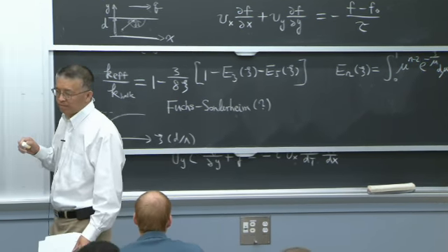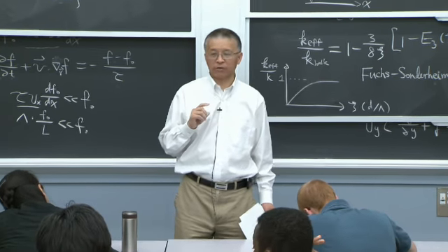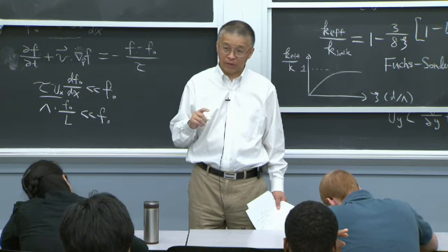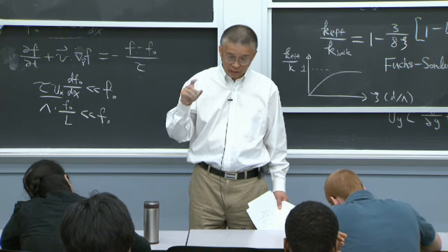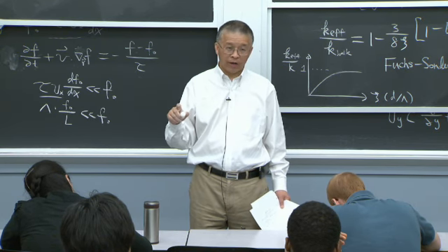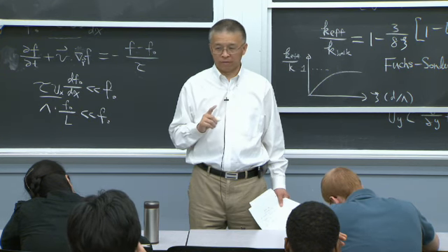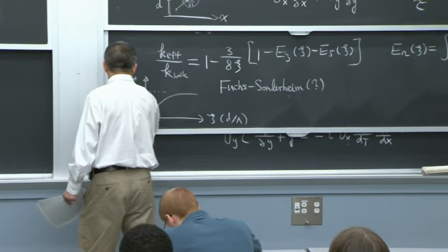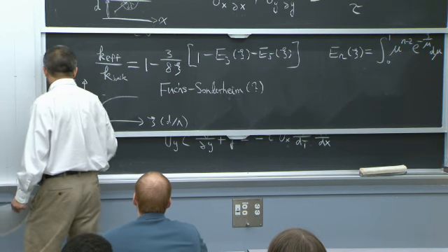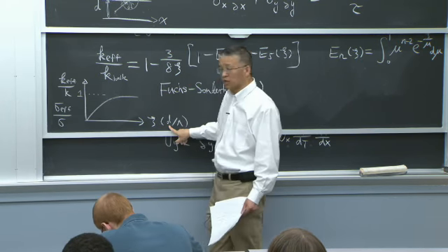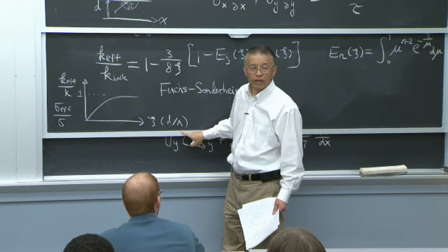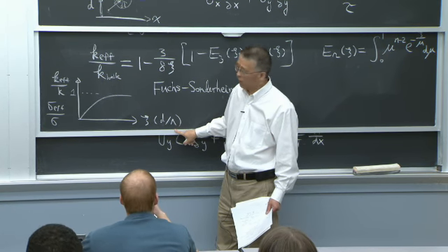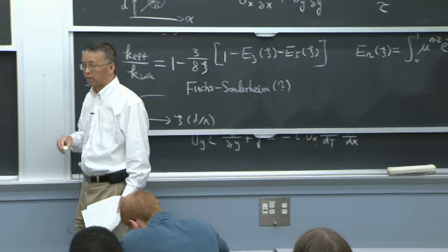It was developed for electrical transport. So the original study was not on thermal conductivity, it was measuring the electric conductivity of films. That turns out to be smaller, and the solution is identical for electrical and thermal transport. So you can also say this could be the electric conductivity divided by the bulk electric conductivity, and the thickness divided by the bulk electron mean free path. You all have the same behavior there, and this is because of the surface scattering.